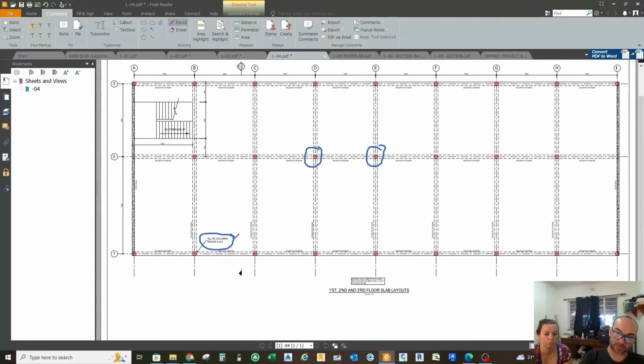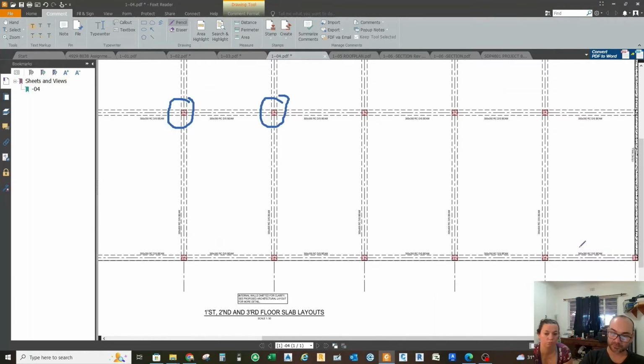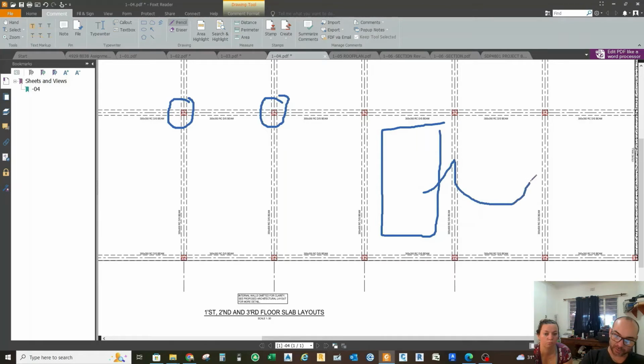It is a flat slab design, but there is, however, a beam grid underneath the slab. So many engineers might tell you that this does not define the flat slab design. However, it has been designed in panels and there is full moment continuity across the panels.